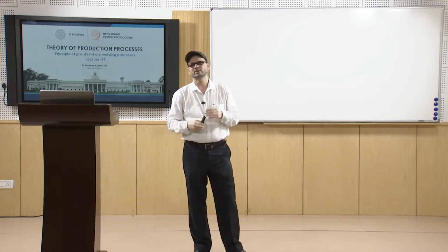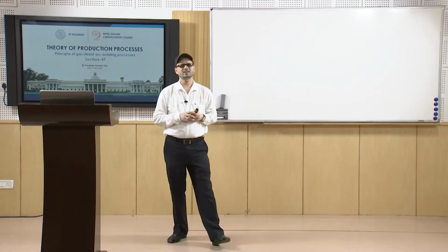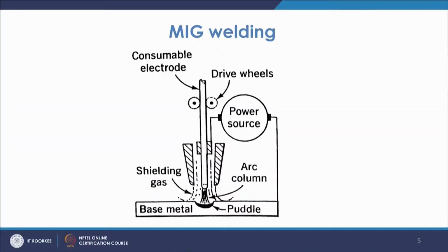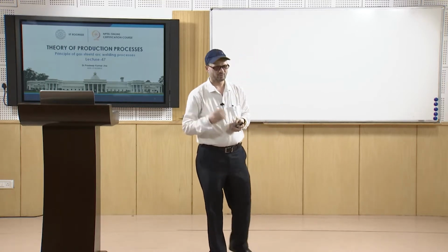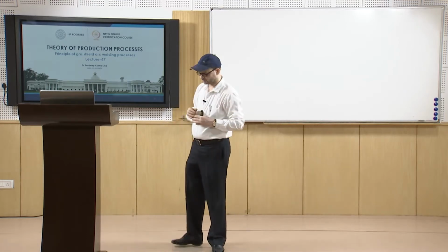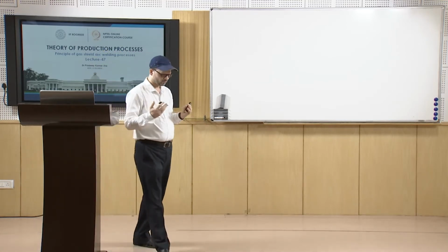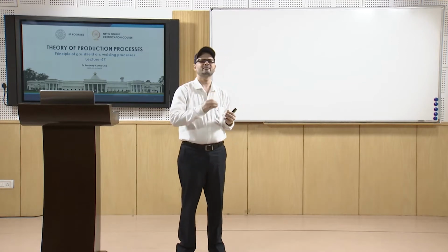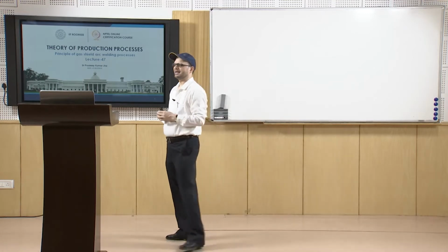All these aspects need to be studied normally in the case of the TIG welding process. Now, next is the MIG welding process, that is metal inert gas welding. As we discussed, in tungsten inert gas welding you have filler metal which is supplied. In this case we use an electrode which is self-consumable, basically a bare electrode, so you do not have the extra filler material.